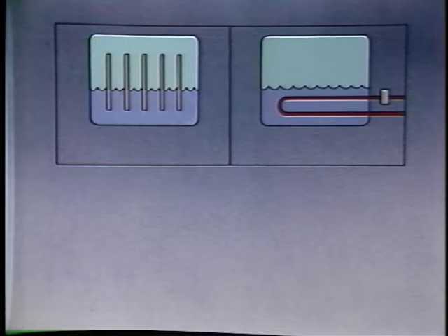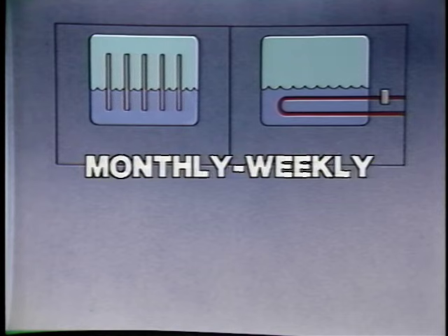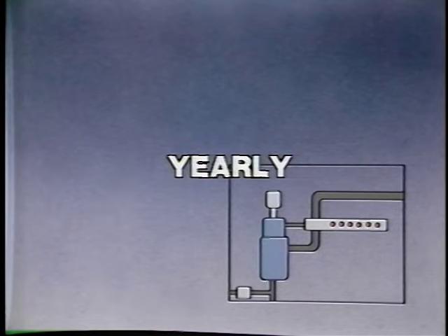Maintenance is an ever-present concern. Humidifier care for all 3 liquid-based methods is completely dependent upon the mineral content of the supply water. Removal of mineral deposits must be scheduled for the pan, hygroscopic elements, and heating coils of the 2 stationary water methods, and from the nozzles and surrounding ductwork of water spray humidifiers. Because of the waterside care that is essential to efficient steam system operation, steam humidifiers require minimum maintenance.